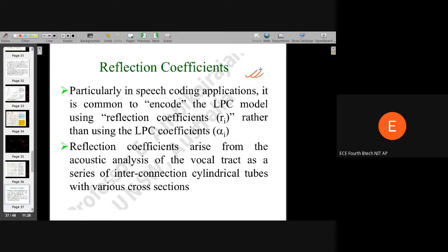Basically, if you have the LP residual, if you estimate the pitch period from that, and if you have your alpha k coefficients, and let's say they are accurate in representing the signal, then you need only say 10 to 14 parameters, and the pitch is another 15 parameters.